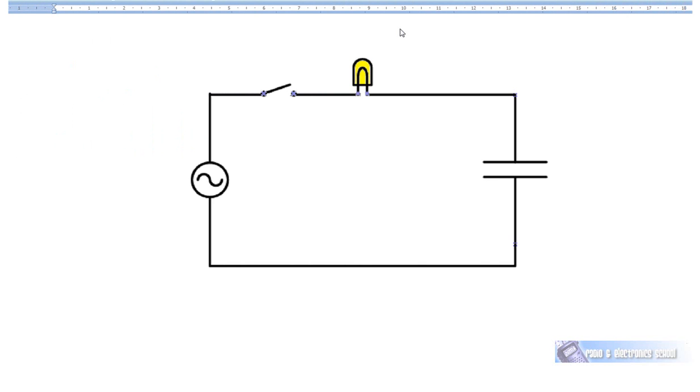When a capacitor is connected to direct current, suppose a battery, then the capacitor will just charge until it reaches the battery voltage, and then all circuit current will stop. Of course, we could discharge the capacitor, but that would be a slow process of charging and discharging, charging and discharging. An easier way to get current flowing at all times in a capacitive circuit is to put alternating voltage onto that circuit, and that's what we're showing here now.